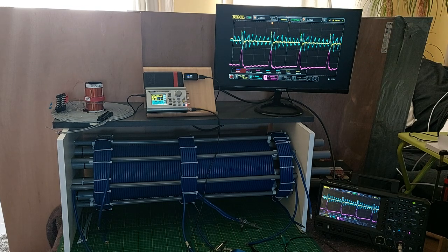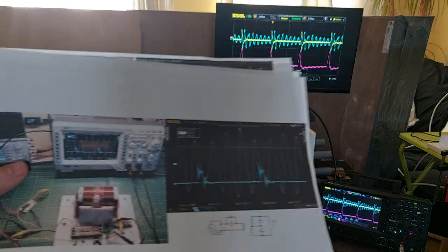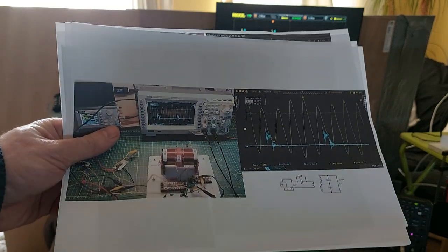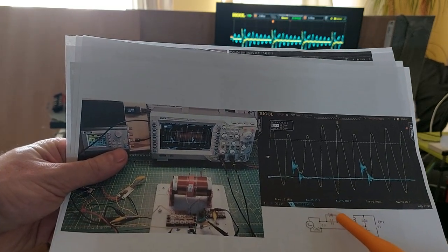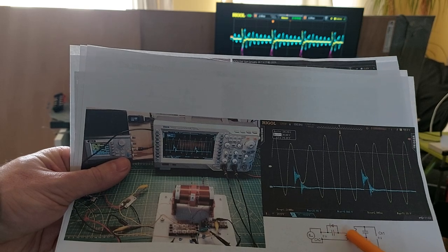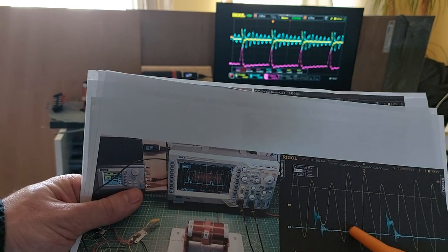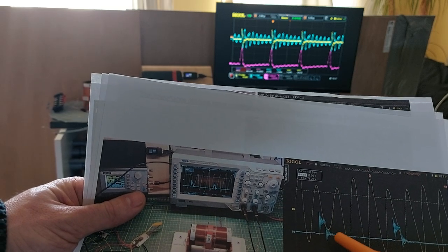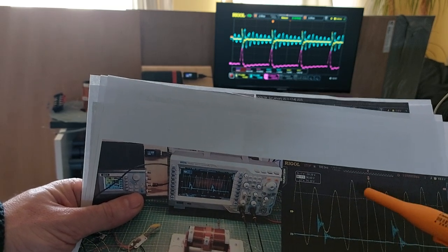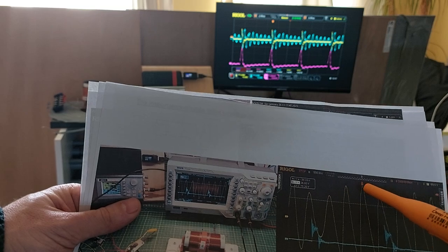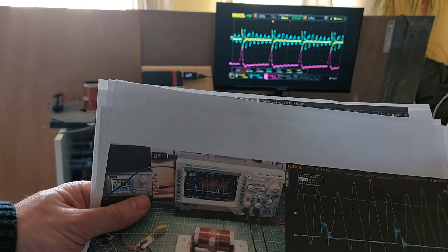In the case you will see in this picture, also linked in the video comments, I placed a capacitor in between the coil and a diode across it, so that I have a more clean input pulse. And in that case, it was even possible to have some slightly underdamped free oscillations.